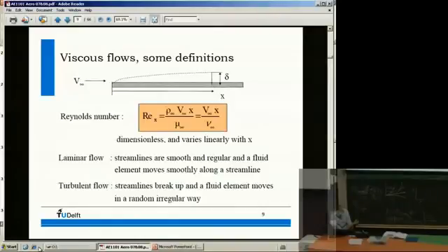So rho Vx is actually related to convection, the speed of the flow itself, so convectional phenomena. Below we have the viscosity coefficient, so that is viscous, diffusion, the dissipation. And the Reynolds number tells you how important convection is over diffusion. So suppose we keep the length the same, a plate of 1 meter in air,